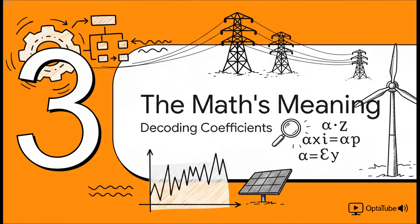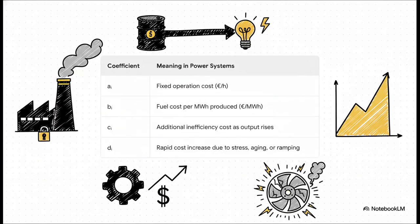Okay, now that we've seen the models, let's actually figure out what all those letters in the formulas really mean. Those letters, the A, B, C, and D, they aren't just abstract math. Each one represents a very real physical cost. A is your fixed cost, the price of just keeping the doors open, even if you make zero power. B is the straightforward cost of the fuel you burn. C represents the price you pay for inefficiency as you ramp up. And D, that's the emergency cost of pushing old gear to its breaking point.